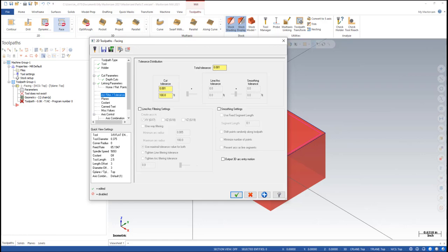However, it doesn't have a whole lot of memory. It's a little over 2 megabytes, which is not a very big NC file. So in the interest of saving space on your controller so that your program will fit, you may want to apply a tolerance or some sort of filtering. Especially on roughing operations, it's not too critical. You could apply a tolerance. You can tell it it's okay to vary 5 thousandths, and the cut tolerance is essentially telling it, from the commanded drive geometry, it's okay to vary up to 5 thousandths in either direction if that helps you to maintain a better cut.